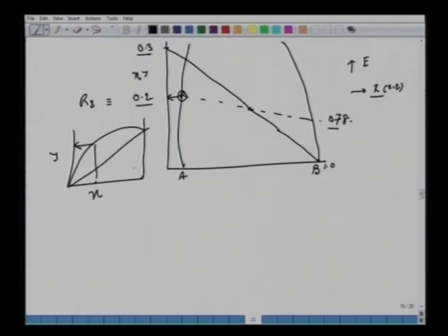Okay, so if we know this xm, again we have a similar exercise. 100 kg, we add 100 kg of feed. Now we add this amount of solvent B. We have R plus E, raffinate and extract, and we have 100 into 0.3 by the mixing rule plus B into 1, and we have this R, raffinate, into 0.2 here, plus E into Y, so this is 0.078.